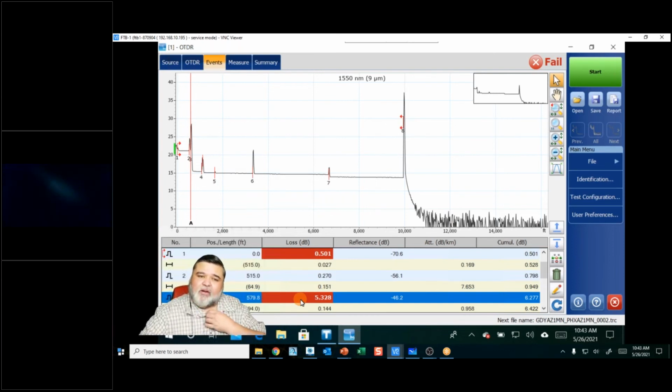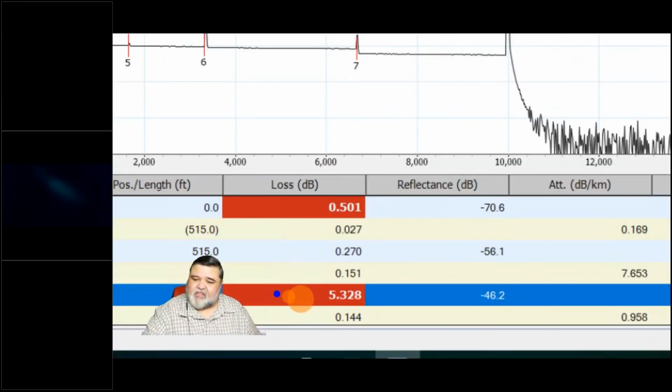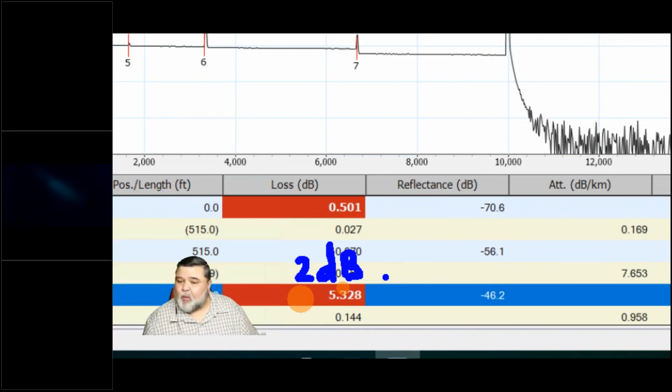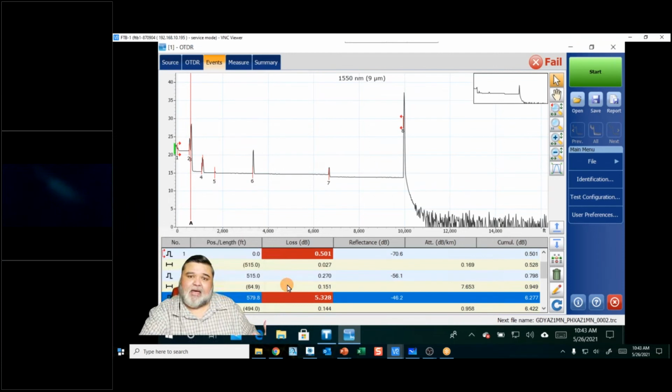you'll be able to understand your loss environments, right? If you know that at this location right here, this is a 90-10 tap and it has 8 drops on it, but you're expecting this to be 2 dB and not 5, then that's important to know, right? So for your analysis and troubleshooting and stuff like that. So setting your thresholds will certainly help with that as well. But it's good to know that information, because most testing is analysis anyways.